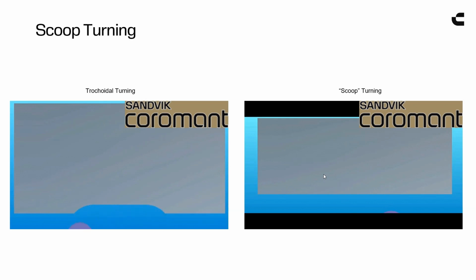So here on the screen, if you imagine that's a round insert going into a turn pocket, going back and forth, that's what trochoidal turning would look like on your CAM software. There is another technique called scoop turning, and that's a variation of the trochoidal technique where you're only down cutting. So you're only diving into the pocket and then you're lifting up at the midpoint and diving in again.